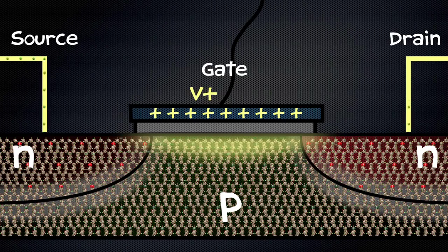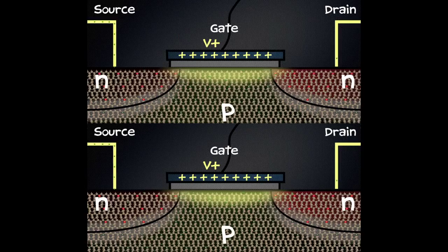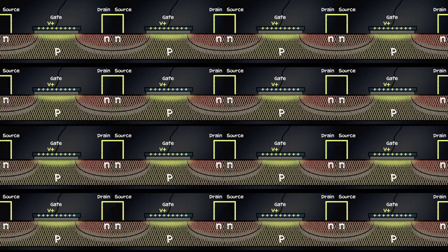Transistors today are only about 22 nanometers wide, which means they're only about 50 atoms across. But to keep up with Moore's law, they're going to have to keep getting smaller. Moore's law states that every 2 years, the number of transistors on a chip should double. And there is a limit. As those terminals get closer and closer together, quantum effects become important, and electrons can actually tunnel from one side to the other. So you may not be able to make a barrier high enough to stop them from flowing. Now, this will be a real problem for the future of transistors, but we'll probably only face that another 10 years down the track. So until then, transistors, the way we know them, are going to keep getting better.